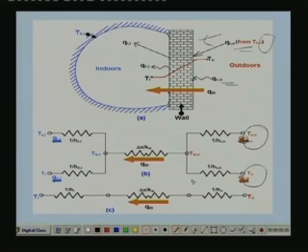the outdoor dry bulb temperature T subscript O. And 1 by HRO is the resistance to radiative heat transfer, and this is the resistance to convective heat transfer on the outer surface side. And through the wall the heat transfer is by conduction, so this is the conduction resistance, where delta X is the thickness of the wall and Kw is the thermal conductivity of the wall material.